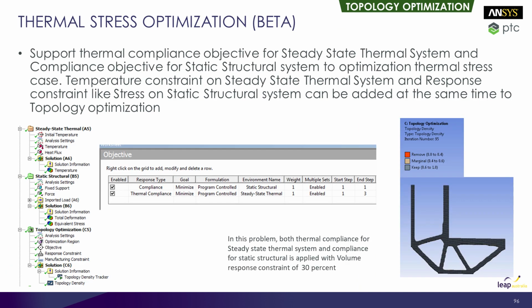And this is a case where we're optimizing for both a structural and a thermal analysis. So there's our thermal analysis, there's our structural analysis, and we want to minimize both structural compliance and thermal compliance. So this is the part that it comes up with using topology optimization.